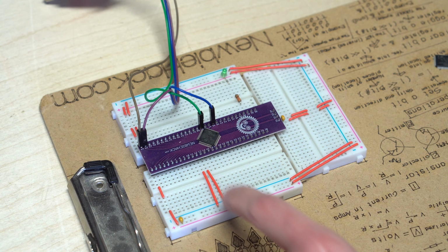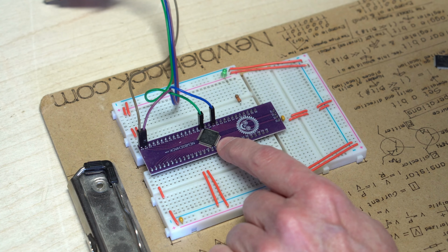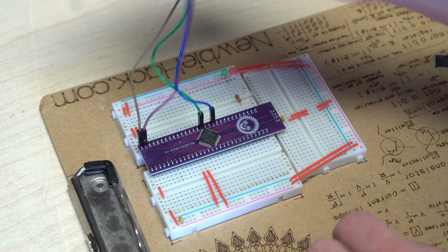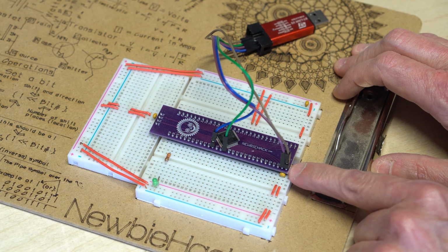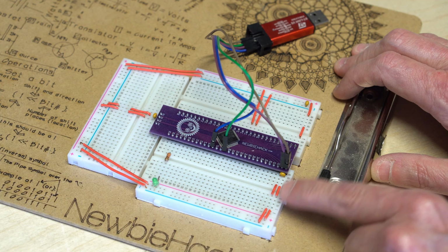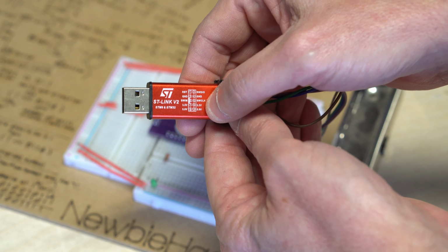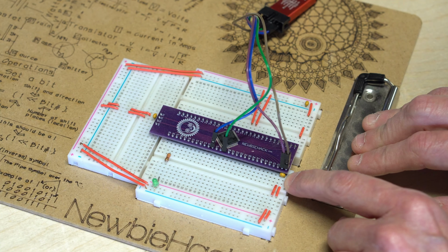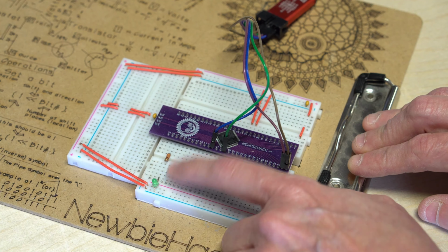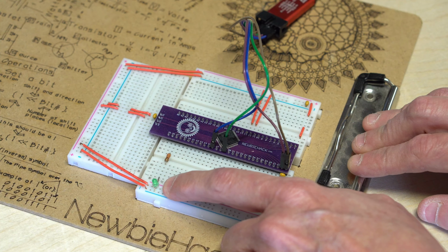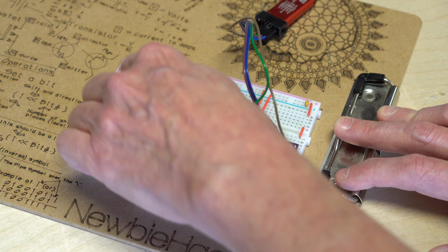The circuit you're going to need is the microcontroller on a breakout board, and the breakout board is connected to 3 breadboards. There are multiple power pins that need to be connected. The power pins are 64 and 63. Pin number 64 is connected to the positive, which is positive 3.3 volts. And pin number 63 is connected to ground, or the negative. I've connected an LED to pin number 37, but you don't need to do this for this particular project. I'm tying the breadboard power rails together using these wires here.